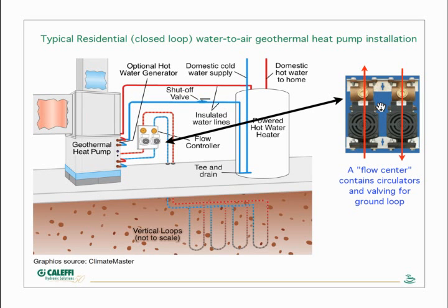loop. It's nice. The one thing that I personally don't get too thrilled about is 4 circulators at 250 watts apiece. That's 1,000 watts going into circulating an earth loop. My reaction to that is design a better earth loop with less power requirements, and that's definitely possible. But we're going to use this as kind of a starting point just so you have a reference. You do see over on the right side of that schematic a water heater.